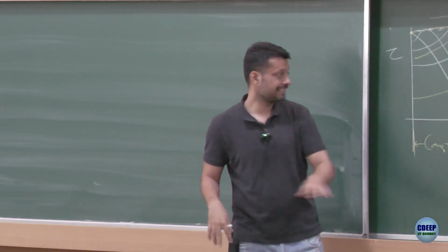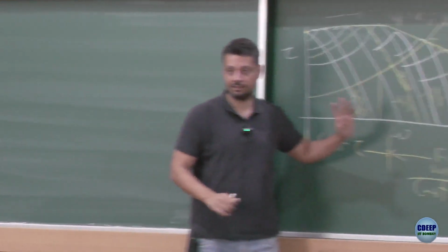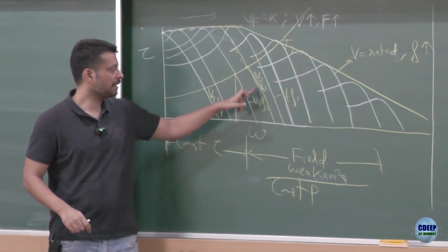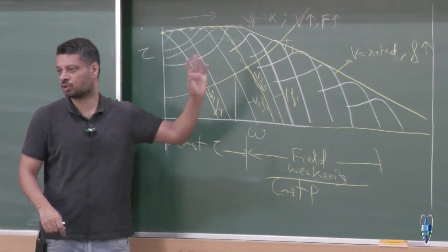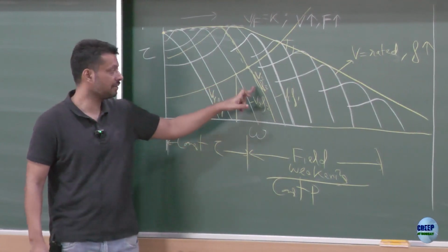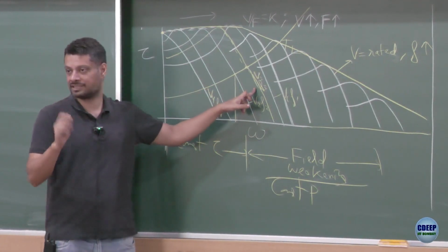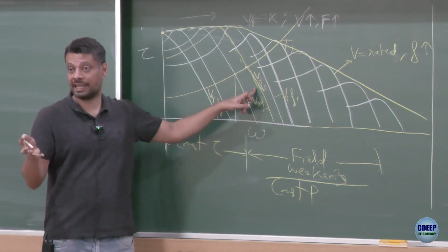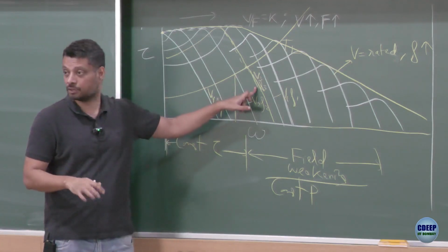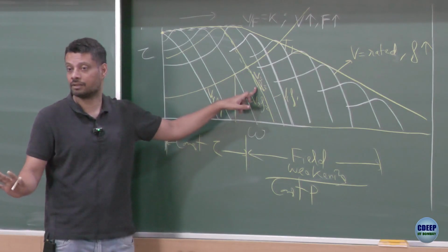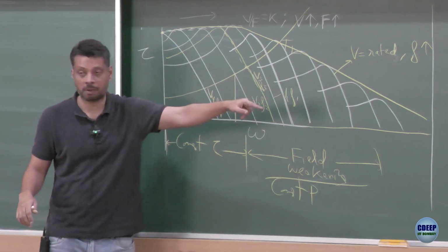So in the setting you were setting, let's say V3 F3, right? Let's say F3 was 45 Hertz, and V3 was corresponding to 45 Hertz. So you were setting F3 on the display and you pressed enter. Now if that drive directly applies F3 to the motor, what will happen? You will have all the problems, right?